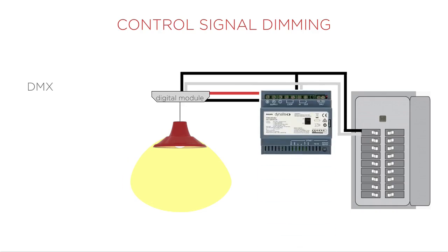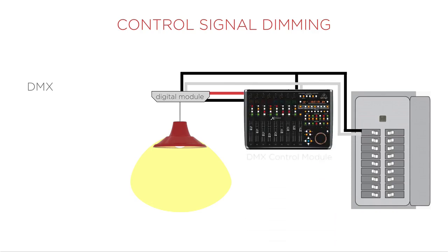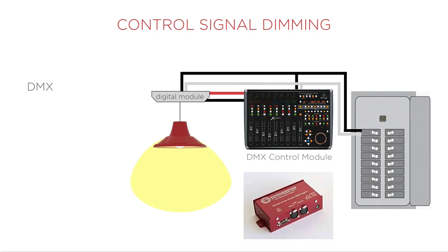DMX is another digital dimming standard, which is commonly used for theatrical lighting, high-end commercial, and LED lights, especially those that have control for color, direction, and shape. There is a Control4 driver for DMX, but it requires an additional hardware device to bridge between the two systems.